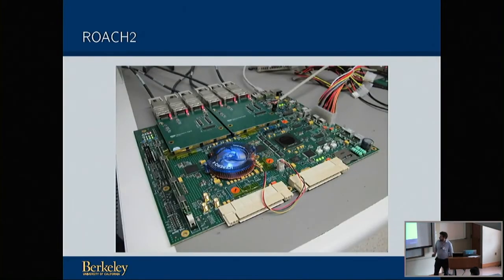What does it actually look like? Well, this. So that's your FPGA, and on all of these boards you'll see the FPGA is always under the biggest heatsink. This is your CPU. These are the ZDoc connectors where potentially you would plug in ADCs. If you want to talk to the CPU, you can use just this 1 gig RJ45 port. So this chip essentially runs Linux. You can log into it like any old machine. It has some RAM here. And then it has these high-speed Ethernet ports.